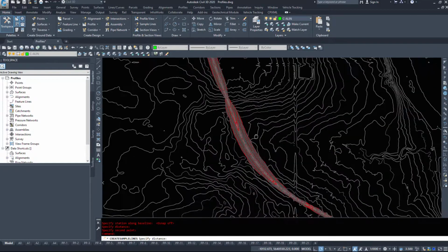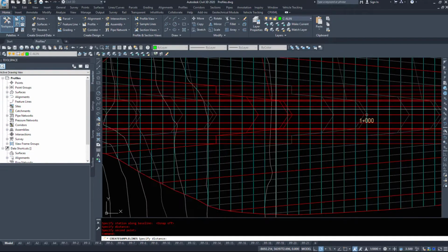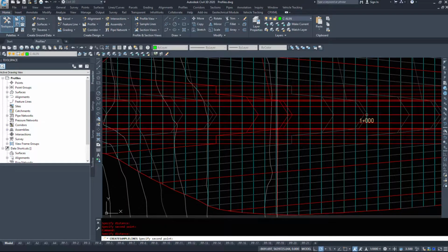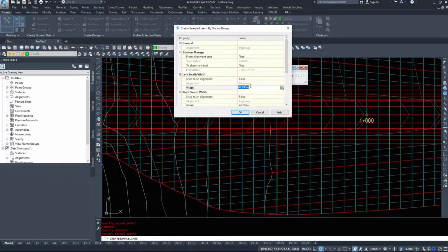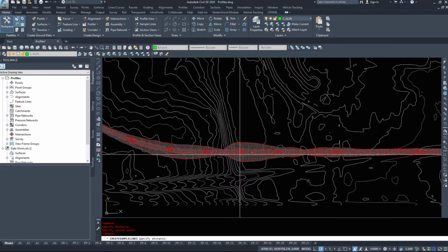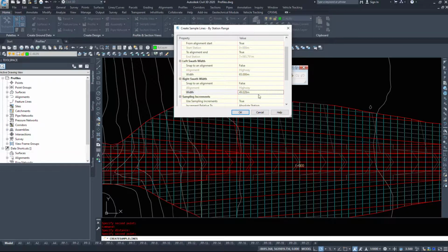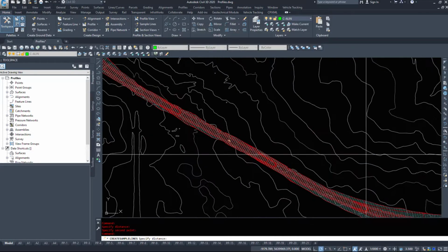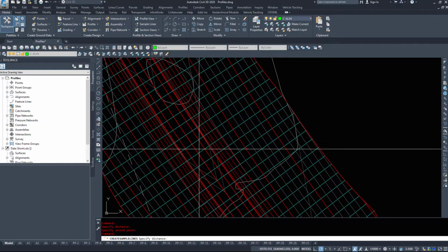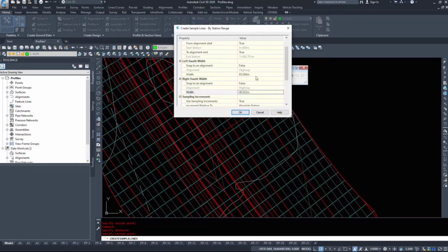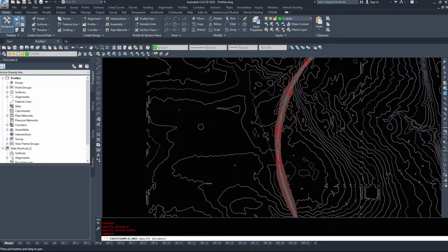That's a pretty wide part. We'll take a look down here, and I'm just measuring roughly from the center of the road to the offset. So we'll go 65 meters on the left, and then 65 meters on the right. Or sorry, we'll figure out what the right is. So we'll check down here. That's about 50 meters. Generally, they're usually the same distance, however, not always. That's 50 meters again.